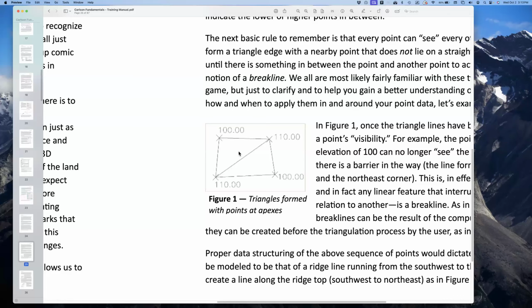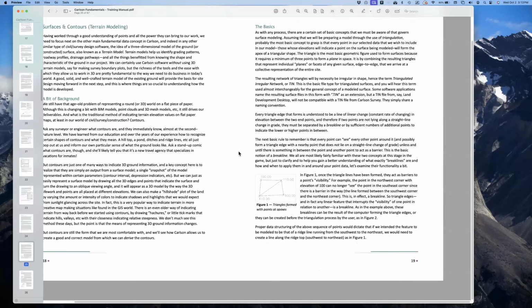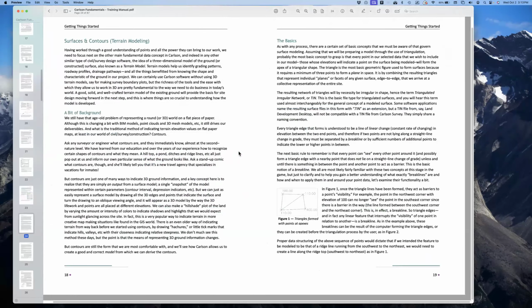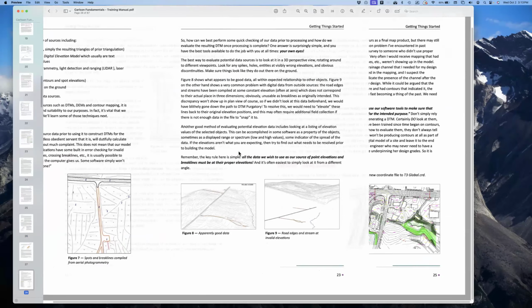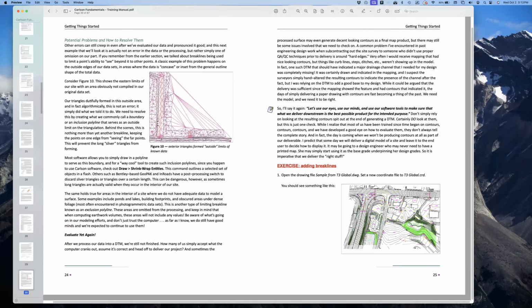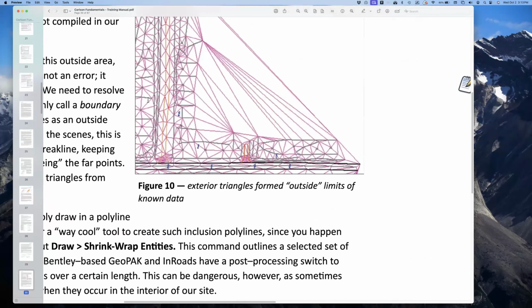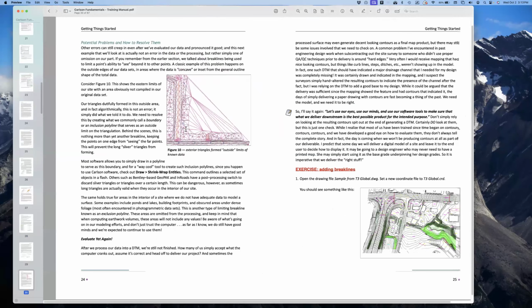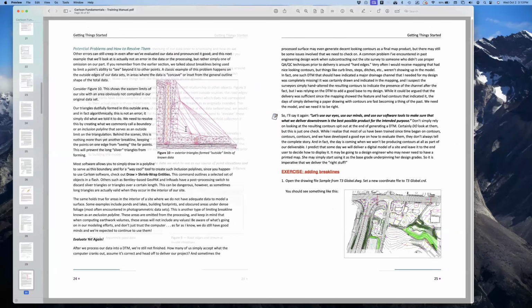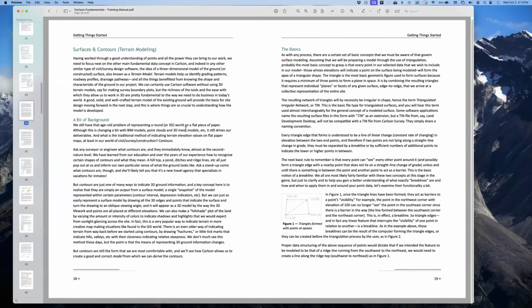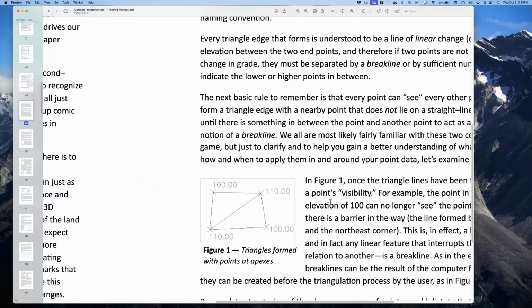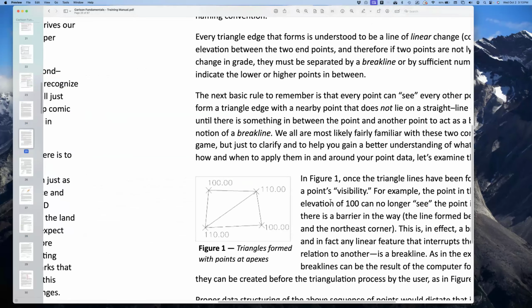So here's just two triangles, but you can see other surfaces like this up here. There's all of those different triangles, all edge to edge the same. All of those edges are common, but they have differing elevations, okay? And we use triangles in this process called triangulation because it takes 3 points at a minimum to define a planar surface.